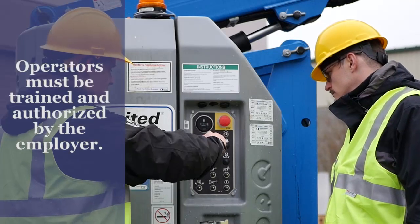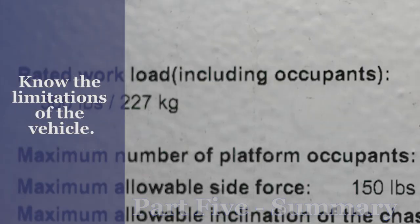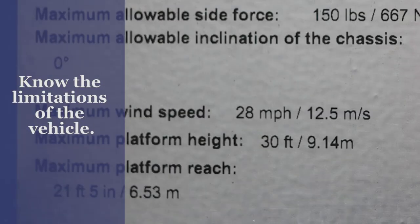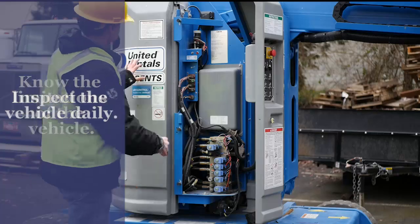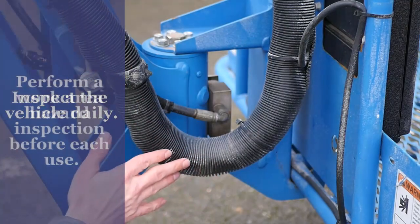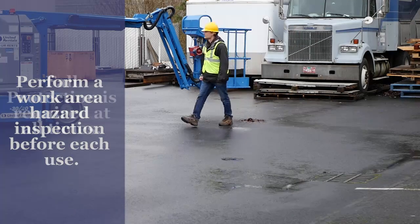Aerial lift operators must be trained and authorized by the employer. Know the weight capacity, maximum slope, and maximum wind speed for the aerial lift you are operating. Complete an equipment inspection each day before use. Survey the work area for hazards before each use.